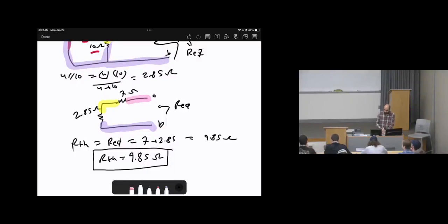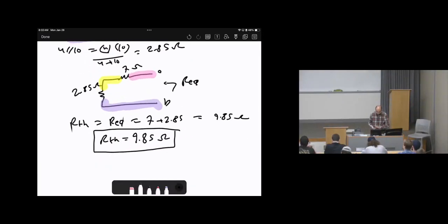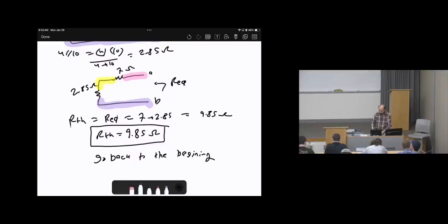Now I just calculated R Thevenin and V Thevenin. Remember, this is not the end. We just found the equivalent circuit. So you need to redraw the circuits, the new circuits, and write the values on it, and see if there are any other unknowns that we need to find. So now let's go back to the beginning of the question. Let me give you a few seconds to write, then we'll continue.